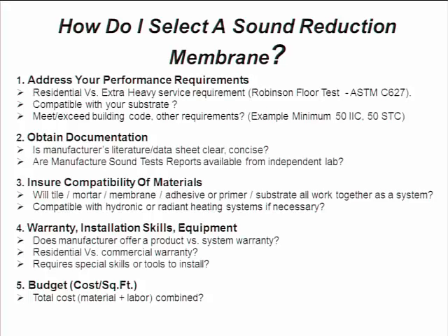As we talked about earlier, there's multiple areas to take into consideration, and bonding is certainly one of them, the membrane to the floor and bonding to that particular membrane. Because in some cases it's required that you use urethanes to achieve that bond. Others are capable of it with primers or with latex modified mortars.